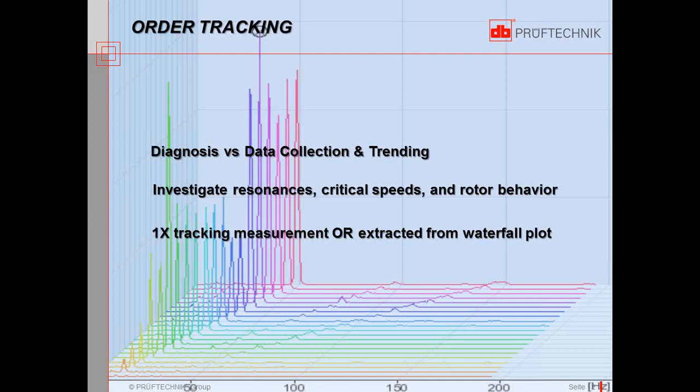The first method, first of all, requires that we have some type of a trigger signal, a tachometer signal. One of the first methods of order tracking is 1x tracking, tracking the fundamental as a function of RPM.